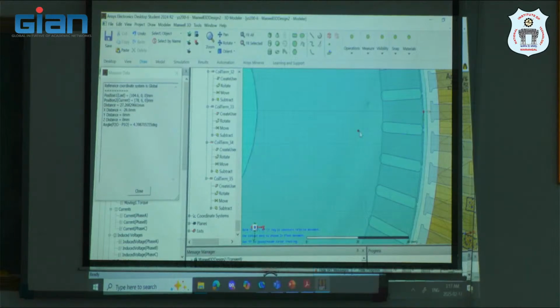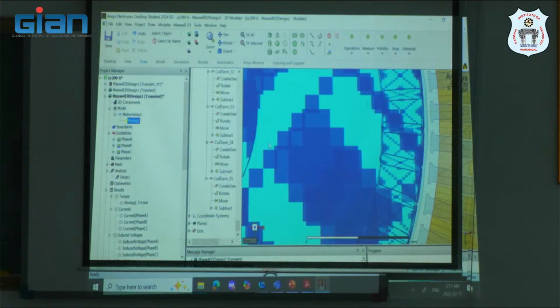And if you want mixed eccentricity, you have to move both a little bit in one direction. Right? So that is how we will do it. And when you do that, because of the software setting, you may have to delete this moving circle first, move everything and redraw a moving block and do the simulation. Otherwise, you will encounter an error in this software.